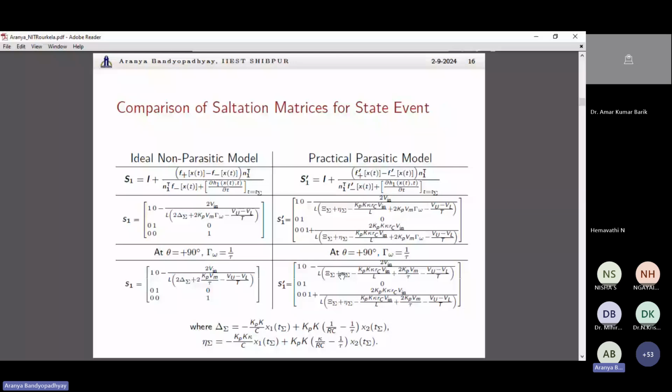Note that the first case of instability manifests in the inverter at the positive peak, at 90 degrees phase angle. So that's why we are going to take that fixed point as a typical case and leave the rest of the 499 fixed point cases. Because this is the frequency at which the period doubling bifurcation, or period doubling type of instability, will manifest for the first time.